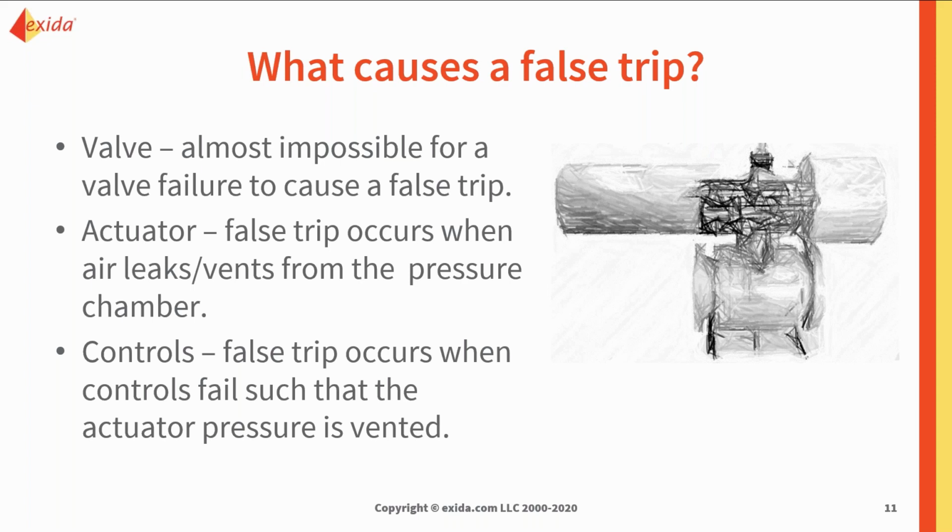This could be something as small as O-rings or seals that are broken or missing or bound together and not performing their job right, leaking, and air is getting out. So it could be something as small as just O-rings, and this could easily cause some false leaks or false trips.